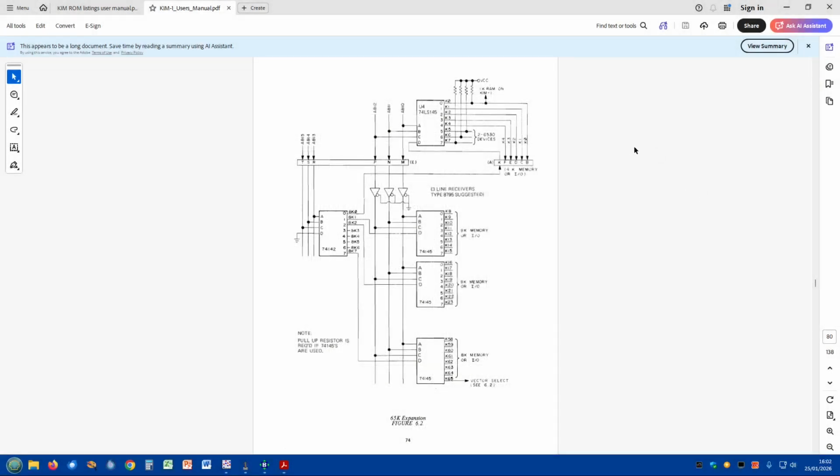Now just popping back to the address decoding. Here's that address decoder up here. And the D line, remember we had to pull that down to 0 to make things work? Well, if you feed that out to another decoder chip and put the high addresses in it, so 13, 14 and 15 into here, that's got 8 different outputs.